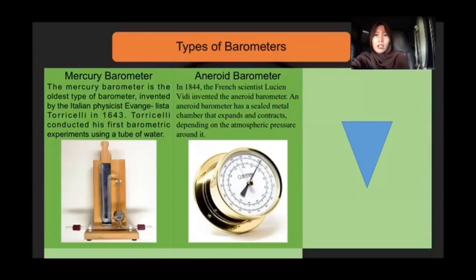The first one has to be quick and easy handling. As you know, mercury is quite poisonous, so there is always a risk with it. Thus, it needs special and cautious handling. However, an aneroid barometer does not have mercury, so one can handle it easily. Moreover, we can carry an aneroid barometer from one place to another easily without any worry of harm to the device.